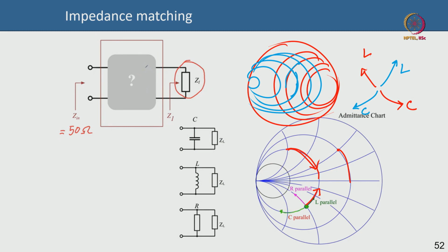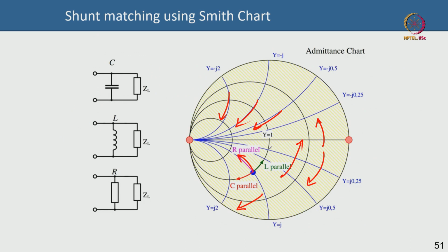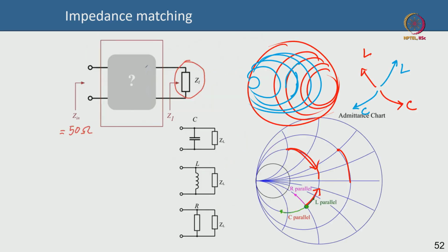And your resistors, which you try to avoid in general, in the traditional Smith chart you will add resistors like that, and in your impedance Smith chart you are going to add resistors like that, okay. So once you are familiar with this movement up and down of adding either a resistor or capacitor or inductor in parallel or in series, you can go from any point in the Smith chart to any other point on the Smith chart, and that is the genesis of impedance matching in Smith chart, okay.